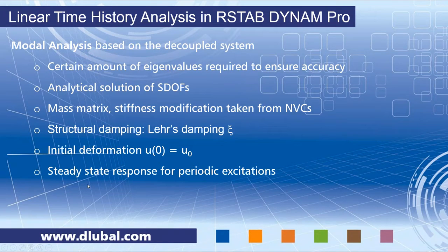We offer the steady state response for periodic excitations. This is only available with the modal analysis. So instead of the complete solution of the differential equation, here only the particular solution is provided. And the modal analysis offers a static correction. This means in case there are any missing masses due to not calculated eigenvalues, DYNAM Pro is able to add those in a pseudostatic way.